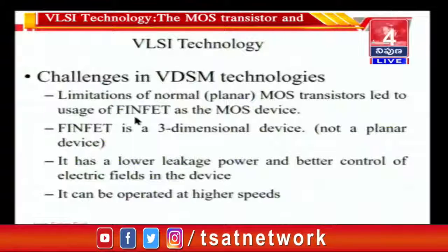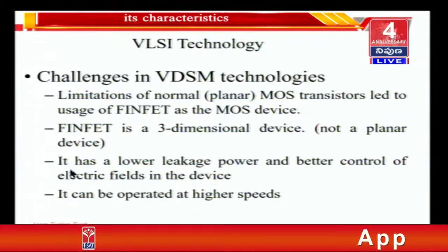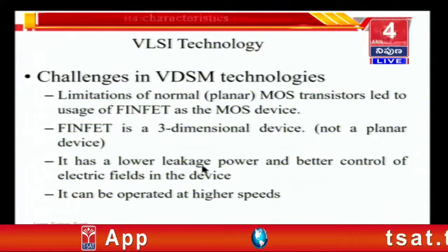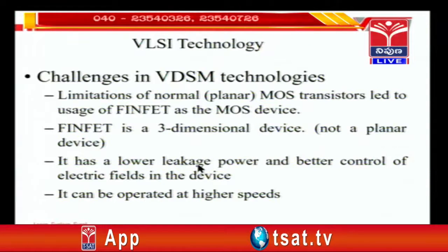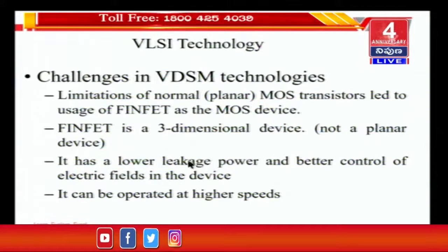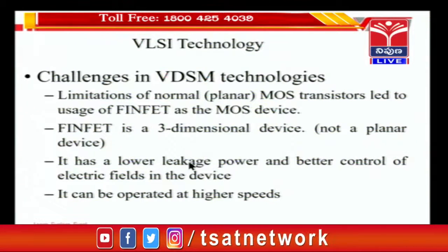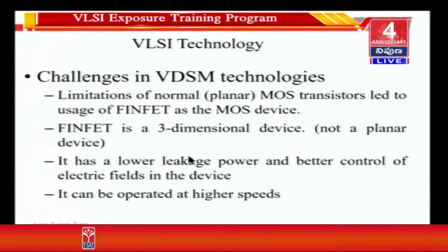Yeah. So FinFET is not a planar device. We can call it a three-dimensional device. And the advantage of having a FinFET is that the FinFET has lower leakage power. Leakage power is the power consumed by the device when it is not switching, either when the output is at logic 1 or the output is at logic 0. When it is not switching, at that time the power consumed by the device is leakage power.